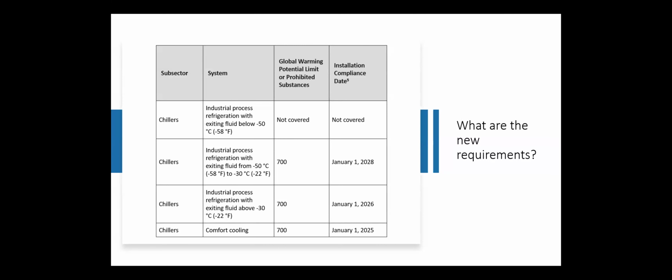Hello, Anna. So when we leave these rated shafts and our provided protection, and let's say we jump into a plenum interstitial space, and it's not ducted return, it's actually a plenum return. Do we need to continue to provide protection for those refrigeration lines? Because that hazard will now exist in the breathable portion, whether it's a heat pump or a fan coil unit or some heating cooling apparatus. It's now in that breathable zone. What are our concerns there?